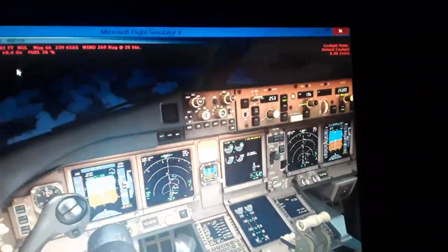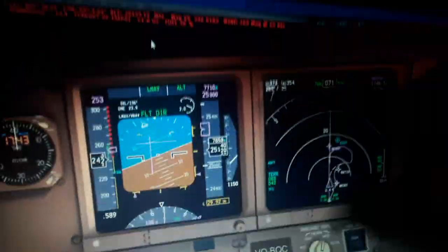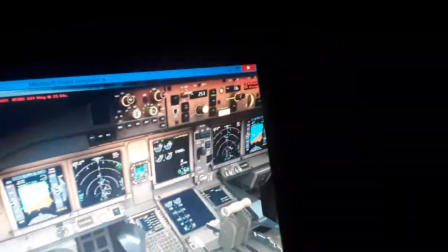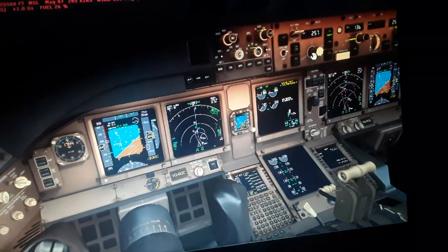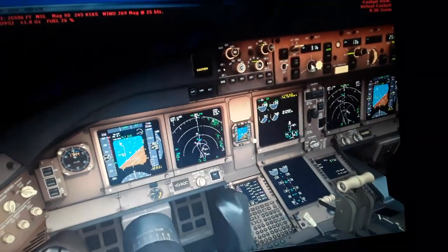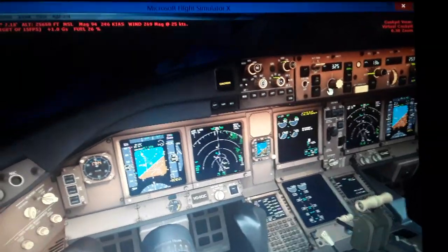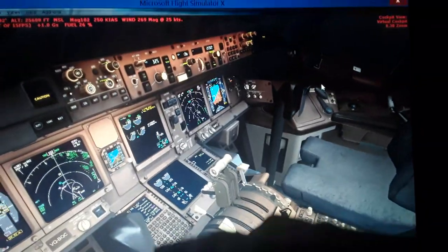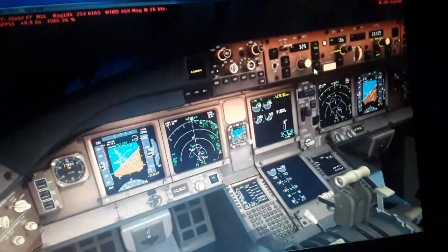So now we need to go inside for the rest of the steering. 35,300, and we have reached our altitude now, 35,300 feet, and we need to manually turn around. So we're gonna increase the airspeed now. Request over here. So our new request airspeed is this, and we retract the flaps to increase the margin.